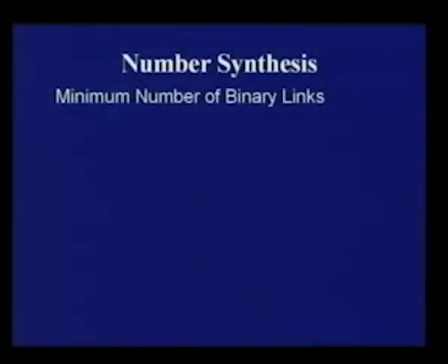However, before we get into the details of number synthesis, we shall first prove certain basic results which are of vital importance for number synthesis. The first of these two questions is, what is the minimum number of binary links that such a linkage must possess? So, we determine the minimum number of binary links in a single degree of freedom planar linkage.